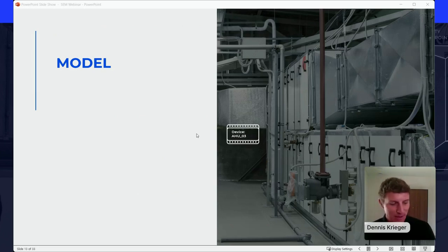And this is probably an often overlooked and frankly pretty challenging step in the process. That's really important, where we're taking this device that represents a controller on this air handler, for example. And when we start, we just know that that device has a name called AHU_03. And for anyone who's done this and knows our industry well, you also know that there's no standard for how we name devices, name data points that's been deployed across all these buildings that we're trying to connect to.